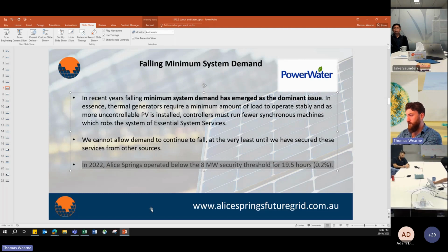But yeah, the business case should be on being able to use it. To use an example like the one we saw before of a sports stadium that's not really using any power in the middle of the day, they probably shouldn't invest in a huge system based on the hope of exporting unconstrained a lot of the time. It's very possible they will still be constrained due to voltage or overwhelming their applicable transformer some of the time, and it's not good to base the business decision on export. It's just good if we can allow it where possible.